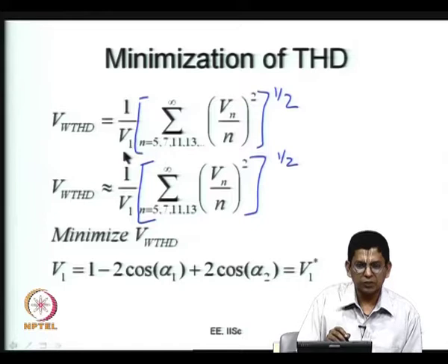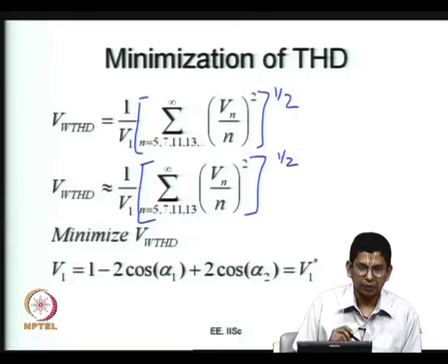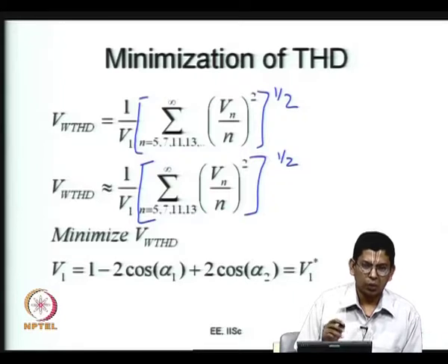So, that is normalized with respect to the fundamental voltage now, and this is called the weighted THD of the voltage waveform, which is equivalent to the current THD. If you multiply the weighted THD by a factor which is roughly equal to the no load impedance divided by the blocked rotor impedance of the machine, you will get your current THD roughly.